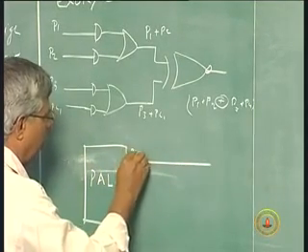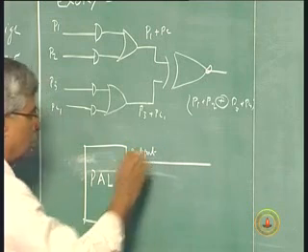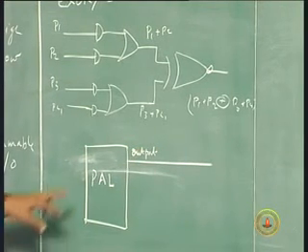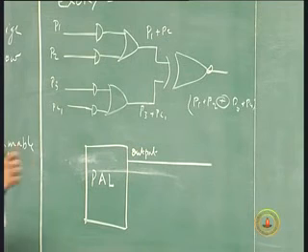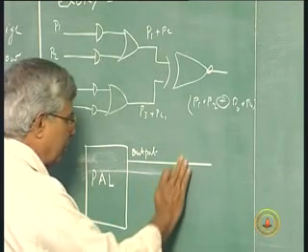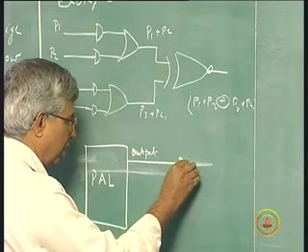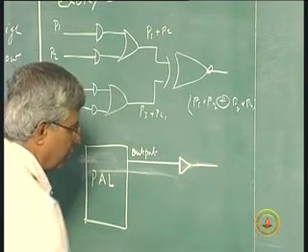And normally it is an output, but I want this to be chosen as an input because I already have 4 of those. This is the 5th one, I don't want this as an output, I want it as an input. So what I need to do is just put a simple buffer here, or an inverter, whatever it is you want.